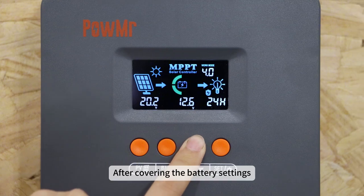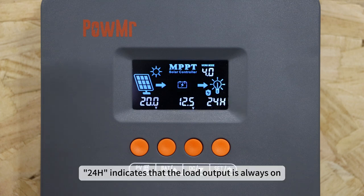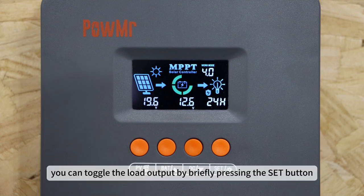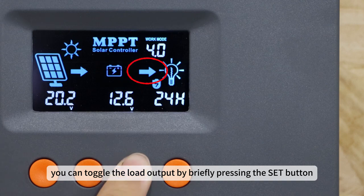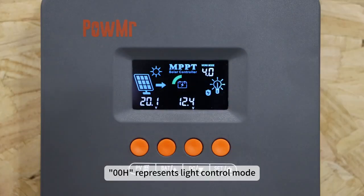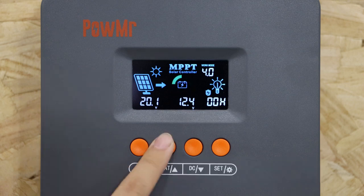After covering the battery settings, let's move on to the load operation mode settings. 24H indicates that the load output is always on. In this mode, you can toggle the load output by briefly pressing the Set button. 0H represents light control mode. In this mode, the controller will turn on the load output after sunset and turn it off after sunrise.